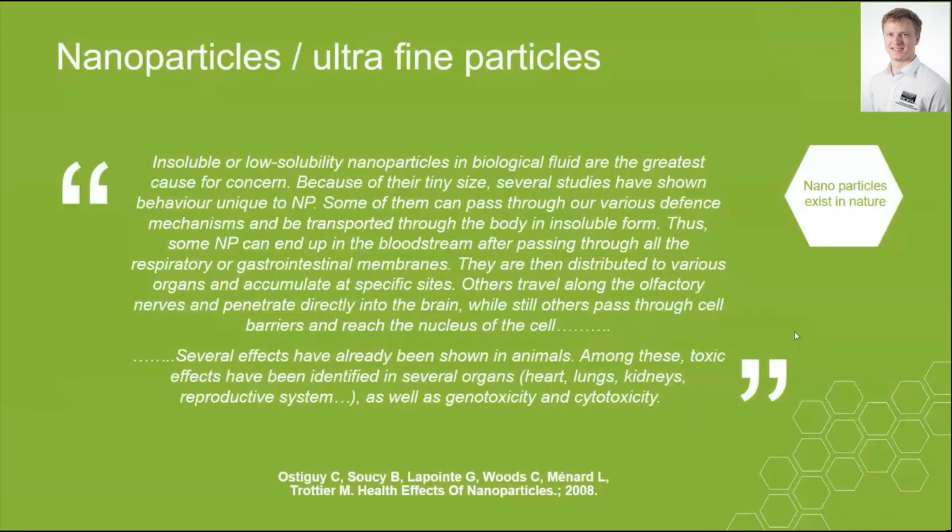Several effects have already been shown in animals. Among these, toxic effects have been identified in several organs: heart, lungs, kidneys, reproductive systems, as well as genotoxicity and cytotoxicity. This shows that emissions from 3D printing processes have the potential to reach much further into the body than conventional processes. It highlights insoluble nanoparticles, which I'd expect plastics from 3D printing to be.